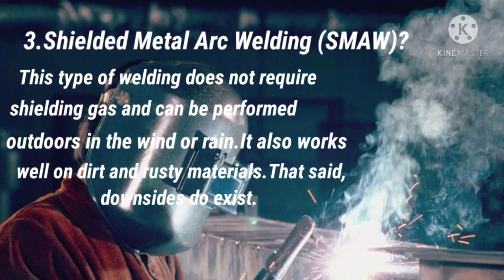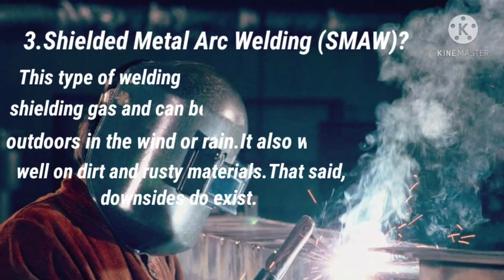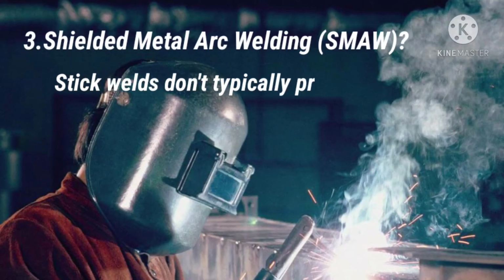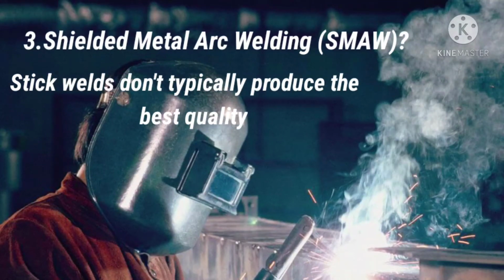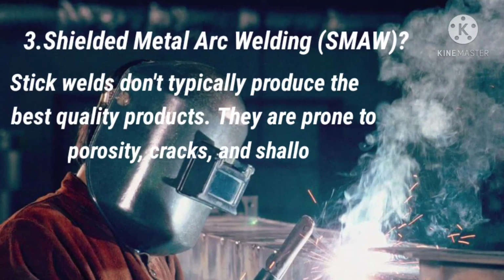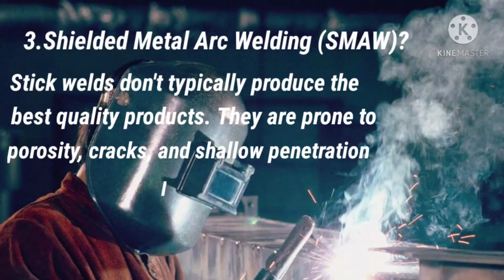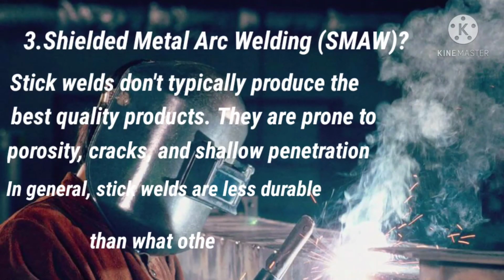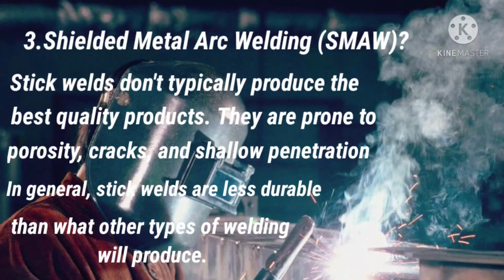That said, downsides do exist. Stick welds don't typically produce the best quality products. They are prone to porosity, cracks, and shallow penetration. In general, stick welds are less durable than what other types of welding will produce.